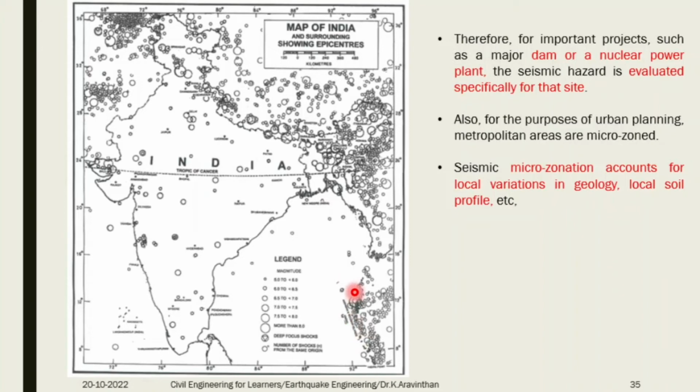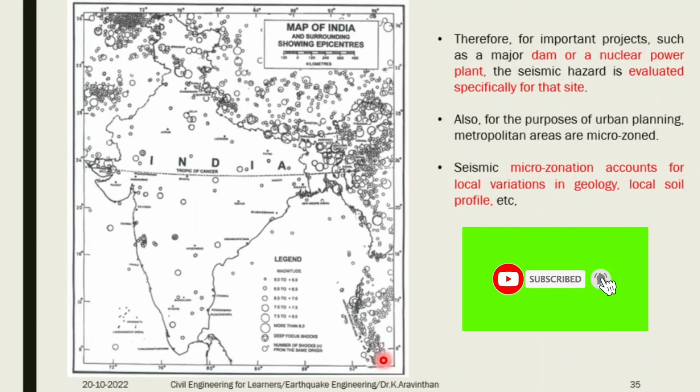And can you see here? They collect all these earthquakes from the past. In 150 years, what earthquakes occurred in India? They take all these parameters and they take the geological effect. India has different types of geology. In the Himalayan region, you have alluvial soil. The geology is different. In the Indo-Gangetic region, you have different soil. In the Deccan Plateau region, we are here in the Deccan Plateau. You go further to the southern side, you have red soil, you have different lithological features. So for all the lithological features, a combined graph is formed.